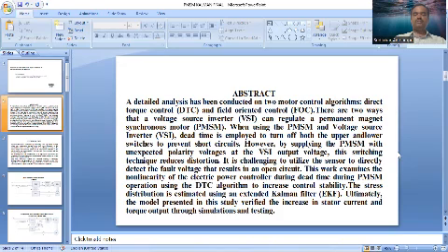motor can be controlled. Here, if the voltage vector is not properly selected, then it will result in various disadvantages like torque ripple and flux ripple, thereby reducing the performance of the motor, and we cannot get a precise control on the speed of the synchronous motor.